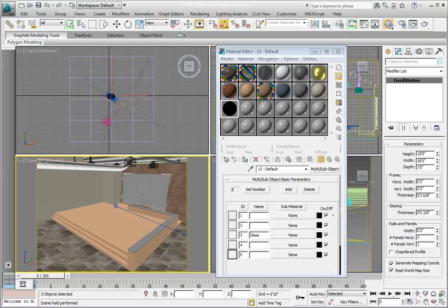If you click over to the Modify panel, you'll see these are parametric AEC Windows objects. These are built into 3ds Max and can come in very handy when working with architectural scenes. In the Material Editor, click Assign Material to Selection in the bottom toolbar. This will assign the material to the 3 windows in our scene. You'll notice that there are triangles in the corners of the material sample window. They've also turned white, indicating the material is now applied to the currently selected object.